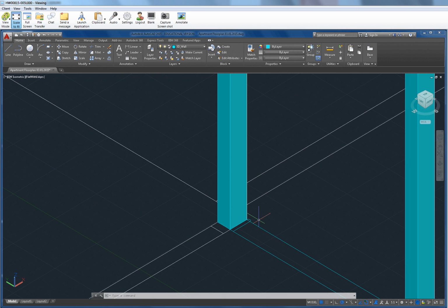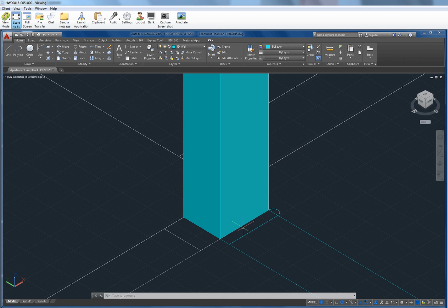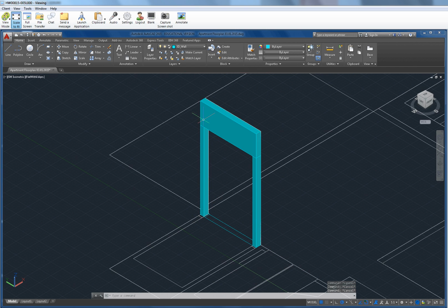Because we won't get that edge profile. So we need to do it through an extrusion in plan. And if it wraps all the way around, we'll look at other techniques, but then we might need to take that same profile and understand how to extrude it in elevation as well, right? Sort of like side elevation.